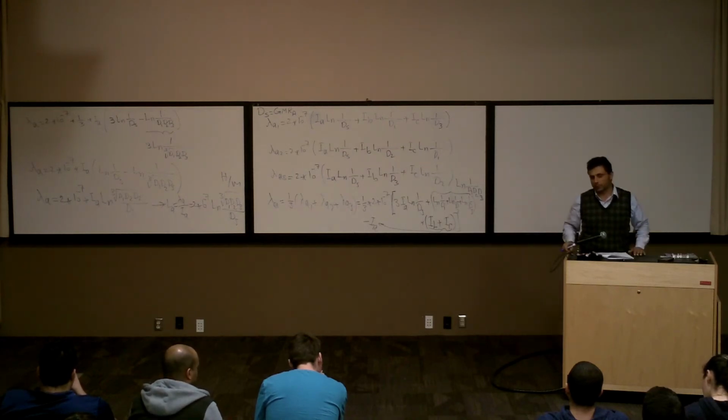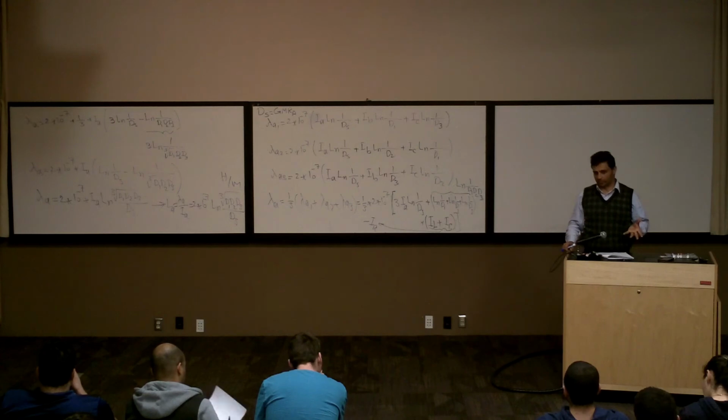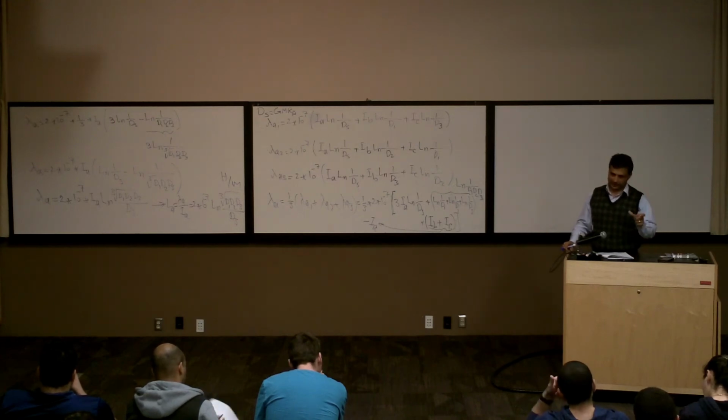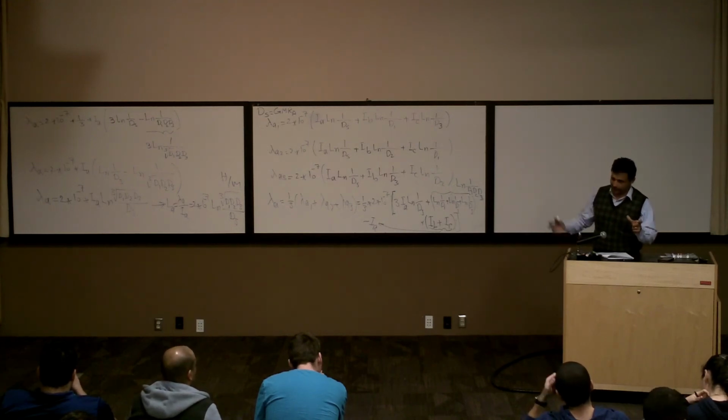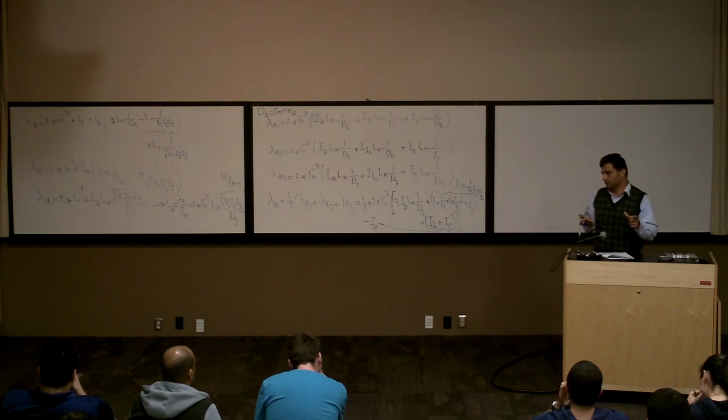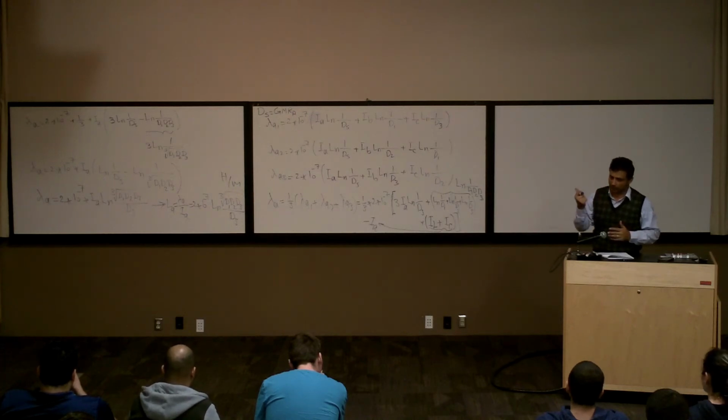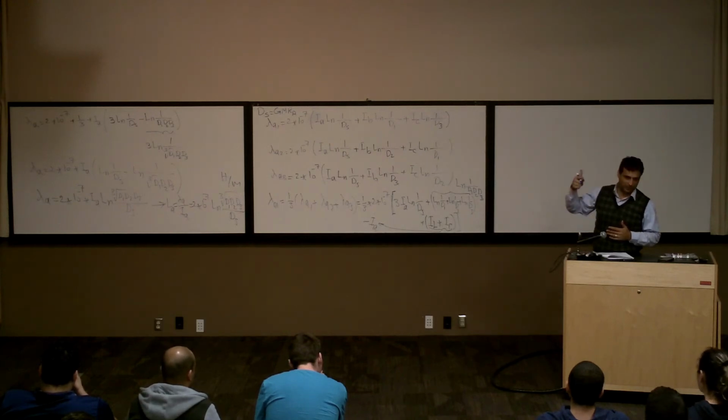If you don't do that, what's going to happen? It's going to burn. Why? Because there is an RI square loss, right? R depends on the conductor and I is the current we are going to pass. So if you keep the conductor small, the cross section is small, R is going to be bigger, right? R is rho L over S, right? If S is small, R is going to be bigger, right?